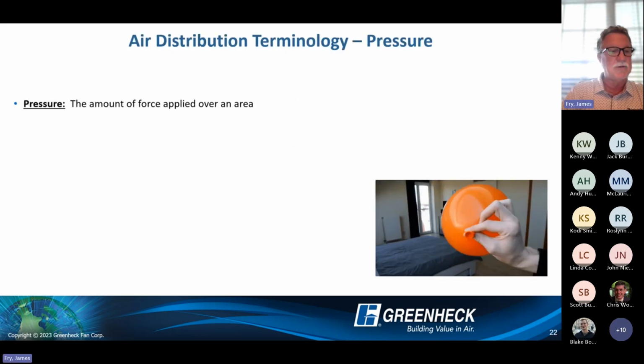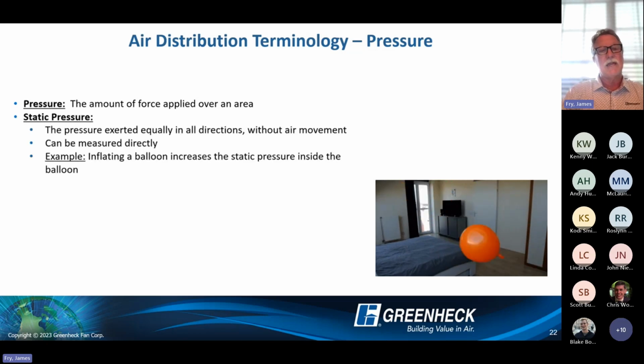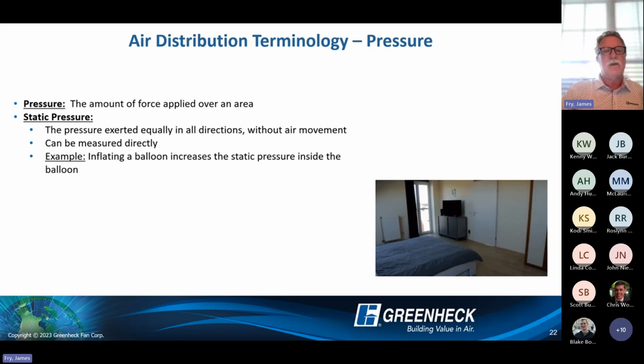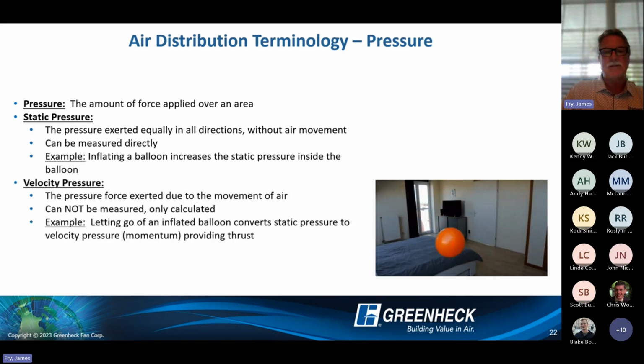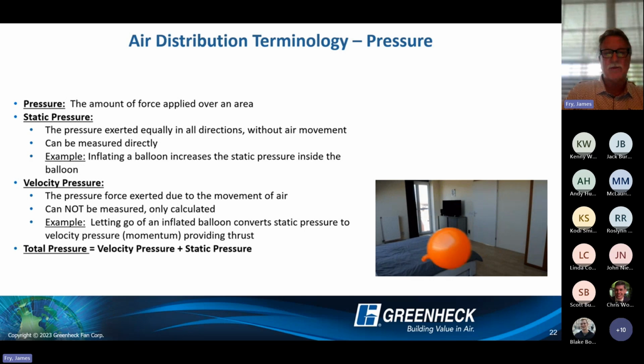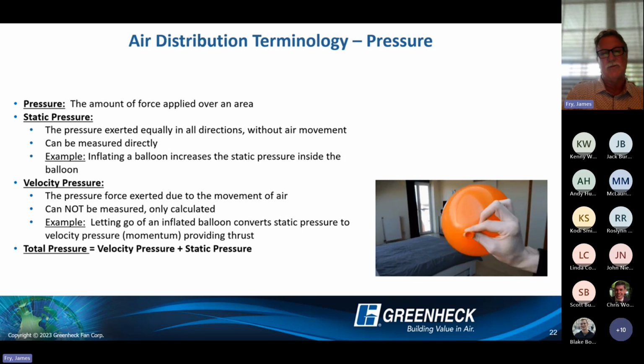Another terminology that you should be familiar with when looking at our charts is pressure. Static pressure is exerted equally in all directions without air movement and can be measured directly. Inflating a balloon increases the static pressure inside the balloon, and velocity pressure is releasing the balloon. It cannot be measured, it's only calculated. Total pressure equals velocity pressure plus static pressure. These will be data points on our performance chart.